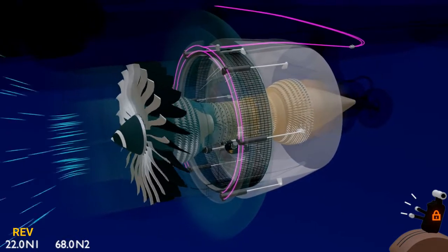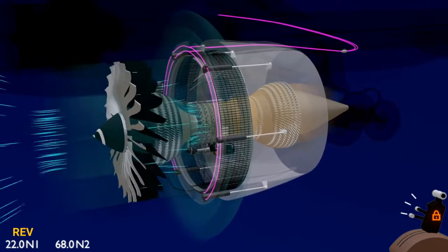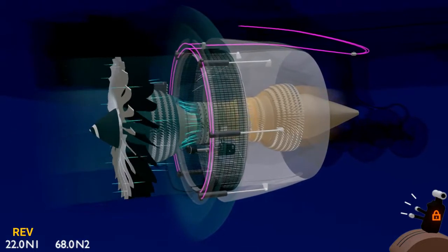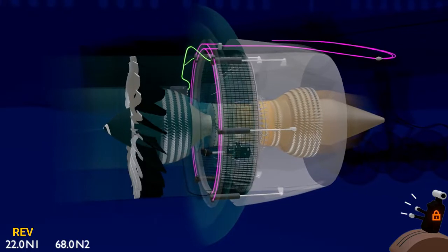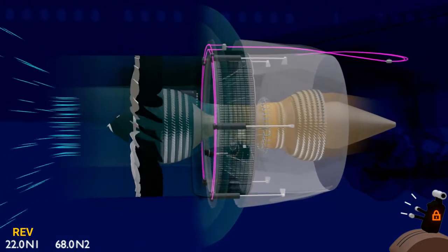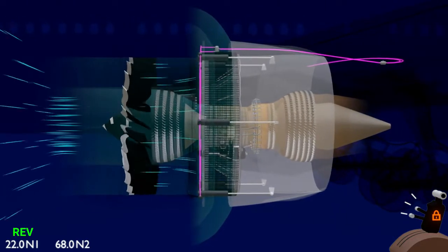The engine bypass airflow that contributes the majority of the forward thrust hits the blocker doors and vacates through the cascade segments. Cascade segments ensure the exit airflow is not turbulent. Sensors on the actuators send the reverser position data to the EEC. Once fully deployed, the amber indication turns green. The forward engine thrust has been reversed.